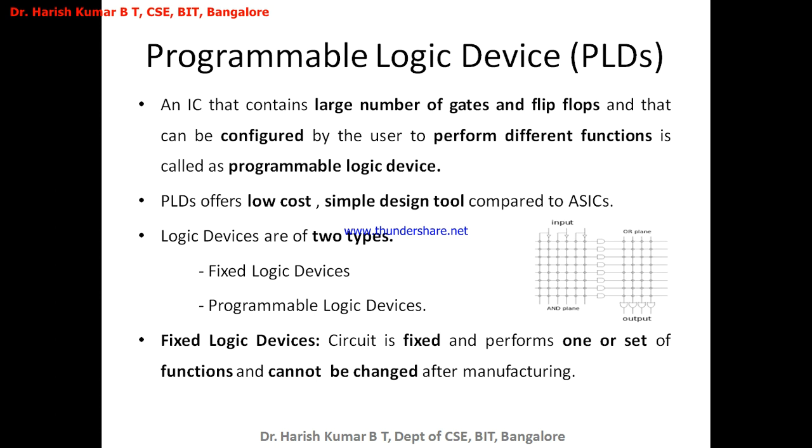Now next is the programmable logic device. These are again integrated circuits that contain a large number of gates and flip-flops. They contain a large number of OR gate planes, AND gate planes, NOT gate planes along with the flip-flops, and these OR, NOT and AND gate planes can be configured by the user to perform a variety of functions and are called programmable, hence they are called programmable logic devices.